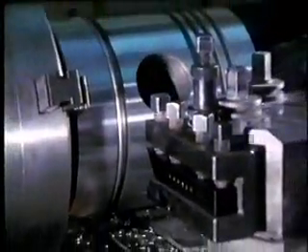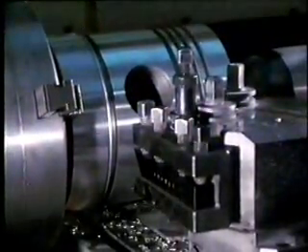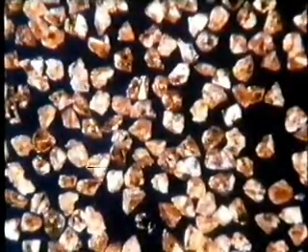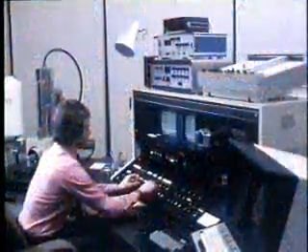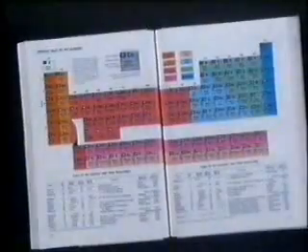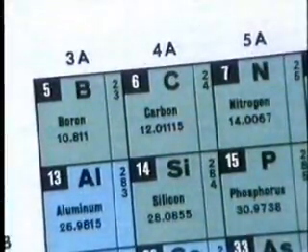Neither diamond nor polycrystalline diamond tool can be used to machine ferrous metals. This is due to a chemical reaction with the carbon which causes metal buildup. However, a new material, cubic boron nitride, or CBN, has been developed for use in these cases. It's the result of a great deal of research based on boron and nitrogen, both closely related to carbon in the periodic table, and using the same technology employed in making synthetic diamonds. CBN is the second hardest material known to man, and it's chemically inert at temperatures below 1000 degrees centigrade.